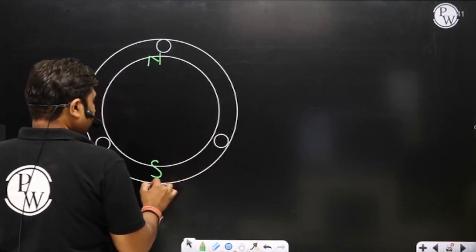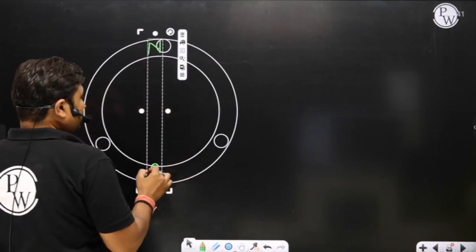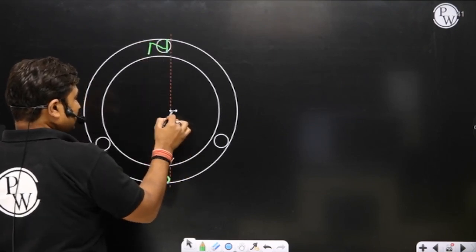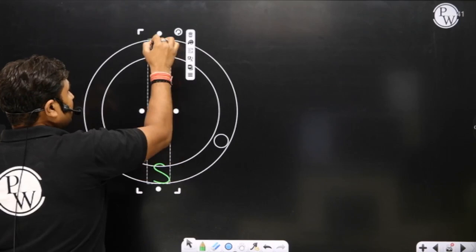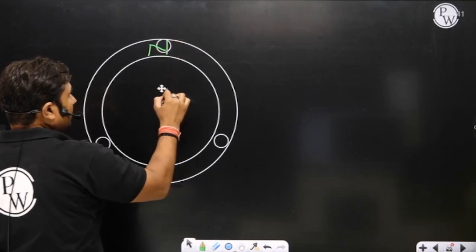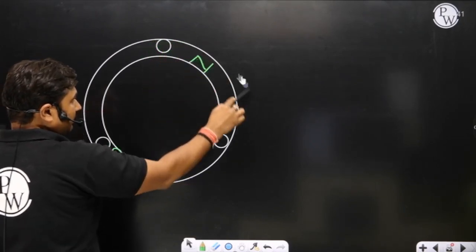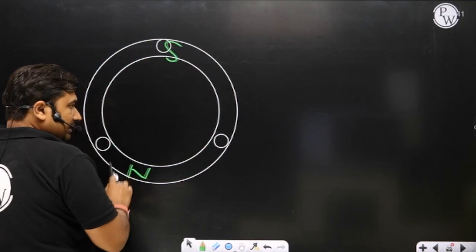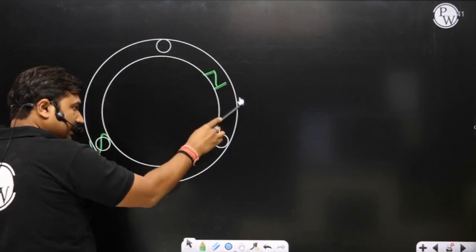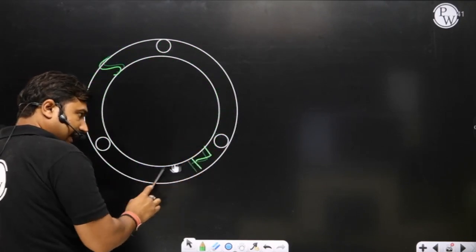So, sir, when a three-phase stator displaced in space by 120 degree is being supplied by three-phase current displaced in time by 120 degree, then a rotating magnetic field is produced. This rotating magnetic field is rotating with respect to rotor winding at a speed of ns.